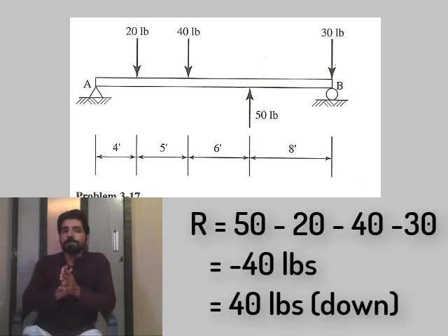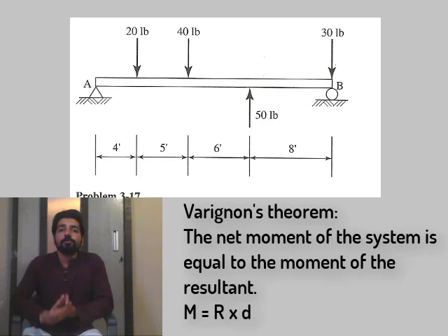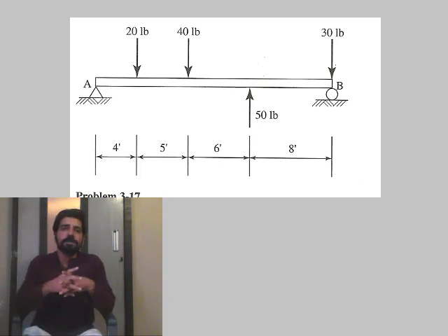Now, because force is a vector quantity, not only its magnitude and direction, but sometimes its position also matters. And we also need to find the position of the body. So now we need to apply what is known as the principle of moments, or also known as Varignon's theorem, to determine the position of the resultant. Let's keep the sign convention same as before, upward positive, downward negative. Let's not confuse ourselves too much right now, but we will just keep upward positive and downward negative.